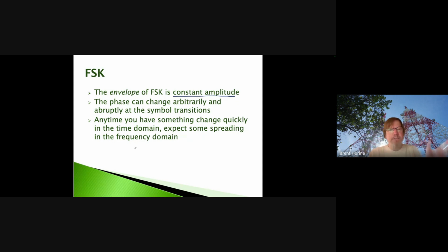Another way of thinking about it is to take that cosine wave, a low frequency one, where the slope as it goes through zero is shallow, and that corresponds to a low frequency. Even though our frequency is constrained to this impulse function in the frequency domain, at a low frequency, if we squeeze those sine or cosine waves together in the time domain, where it's crossing zero is getting steeper and steeper.